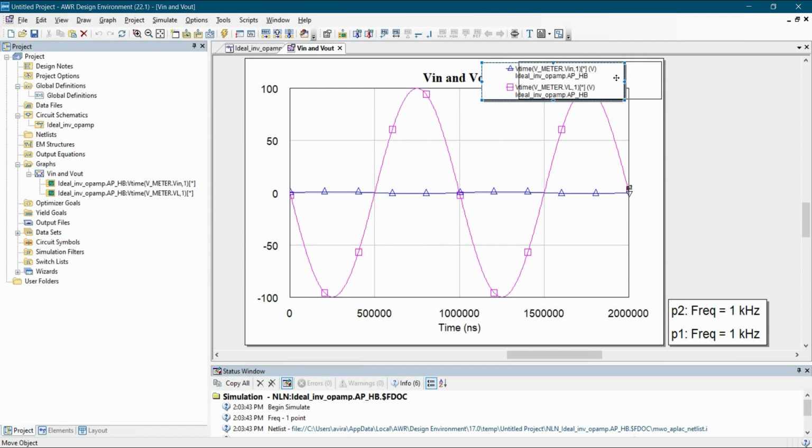So as of now, the input voltage is too low. That's why we can't see the swing exactly. So we have to just make this plot a two-axis plot. So here we have the voltage range from -100 to 100. So we are just going to shift this to the other side of the plot, and here we'll have the input. So we can basically see and compare what is the exact voltage in terms of its value.